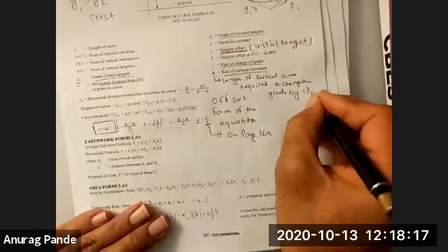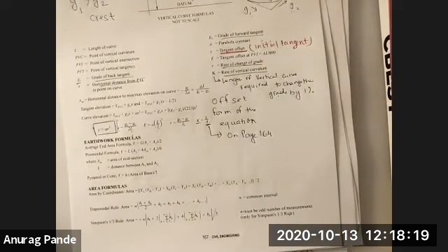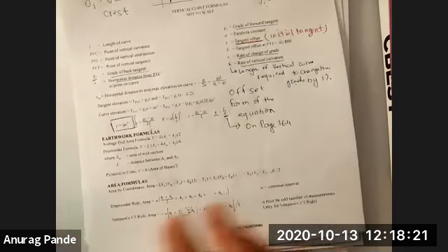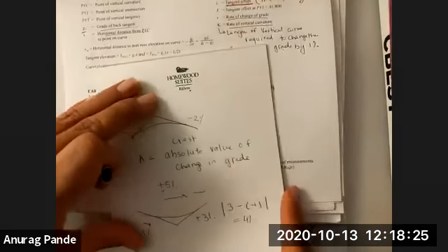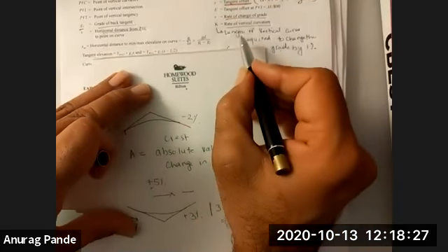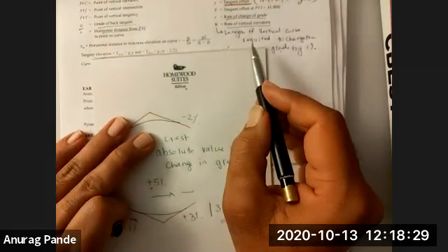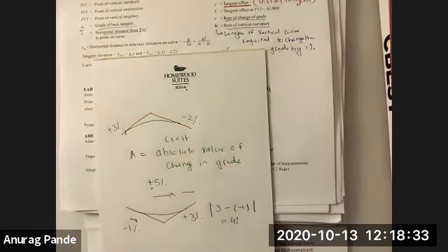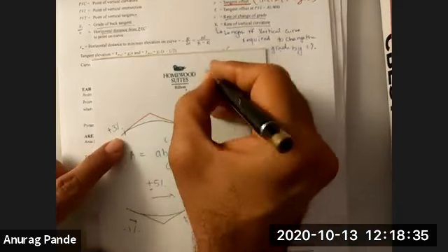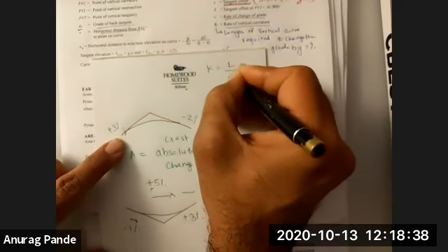Why is this a good definition? Let's think about the examples that we covered earlier. Remember, the K value is defined as the length of vertical curve required to change the grade by 1%, and that K value is defined as L over A.